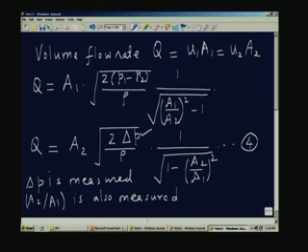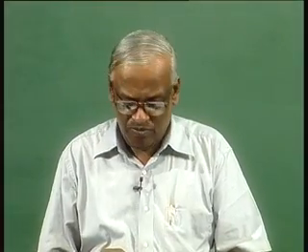In order to make this equation 4 valid for a real fluid flowing through the variable area device, we can introduce a coefficient of discharge. So, what I will do is simply multiply this by C, a coefficient which is chosen such that the actual volumetric flow rate is given not by the ideal expression, this we will call the ideal expression, but by the ideal expression multiplied by some coefficient which is to adjust for the non-idealness of the flow.